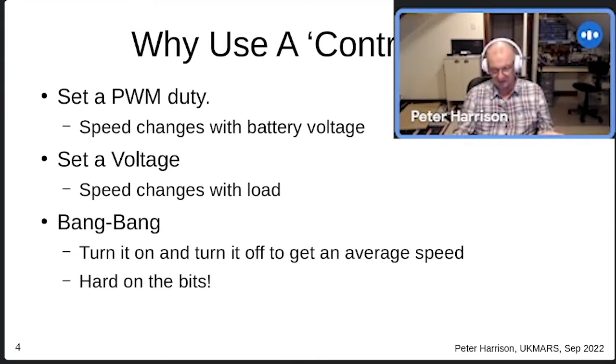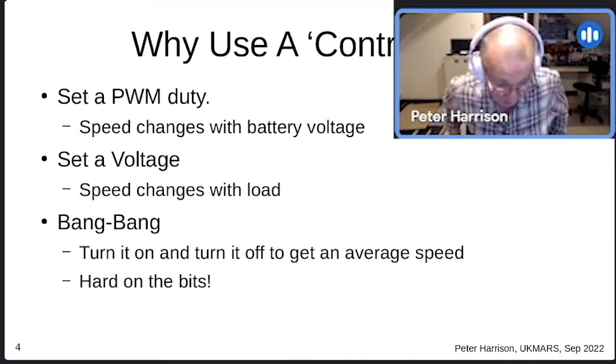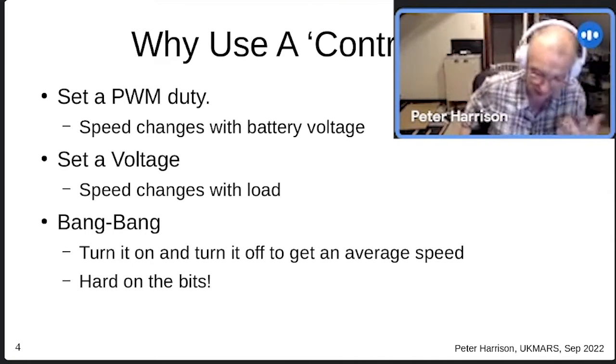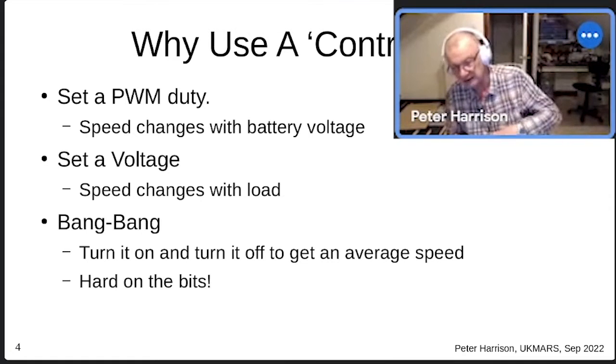The same thing applies to rotational motion and steering and all the other things, but just for the time being, we'll consider the forward motion. And the controller's job is to put an appropriate pulse width modulation duty cycle to the motors. A naive approach would be to use the PWM setting in your processor and say, well, I want it to be 50% or 70% or whatever.